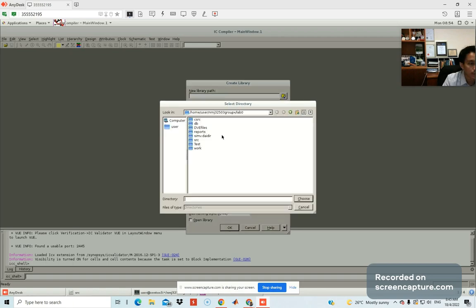Okay, still under EDA. You browse for EDA, and then ref, and then MW library and SC. So under SC we have cell. Okay, we have FRAM, and then we have LM. So we just select the SC folder. Okay, and then you choose it.